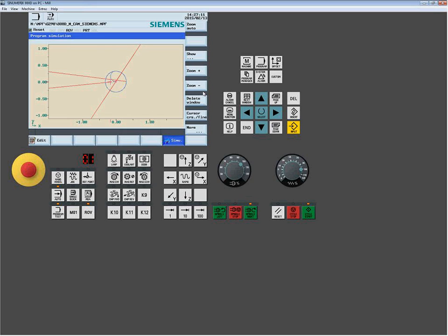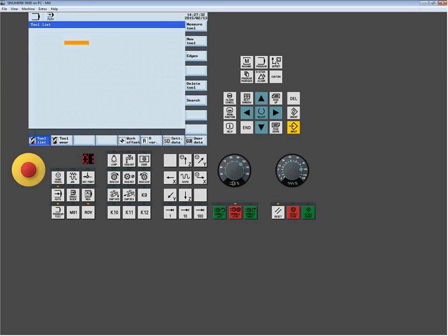On this, you can really start to see it. Let's move over a little bit. I want to get right in here. All right. So now see, all I did was, in this case, I put 25 thou, a little larger than I would in real life. I wanted you to get a chance to see the different cutter paths. So normally, this is how most guys run their machines when I'm dealing with CAM, and I'm outputting cutter compensation.